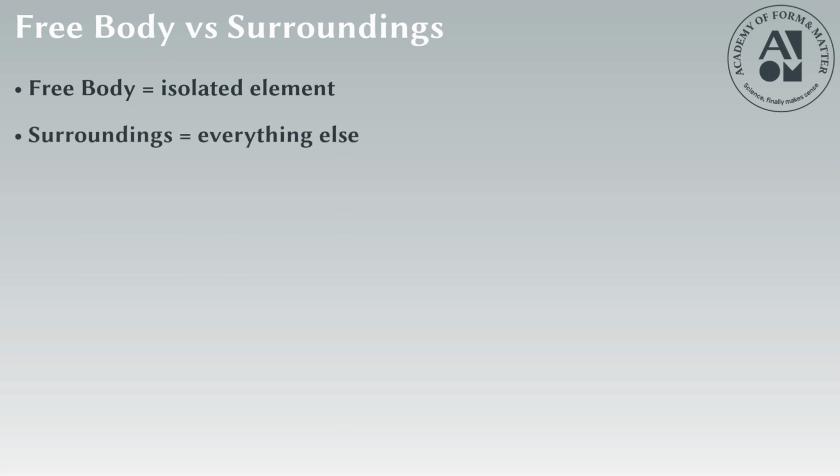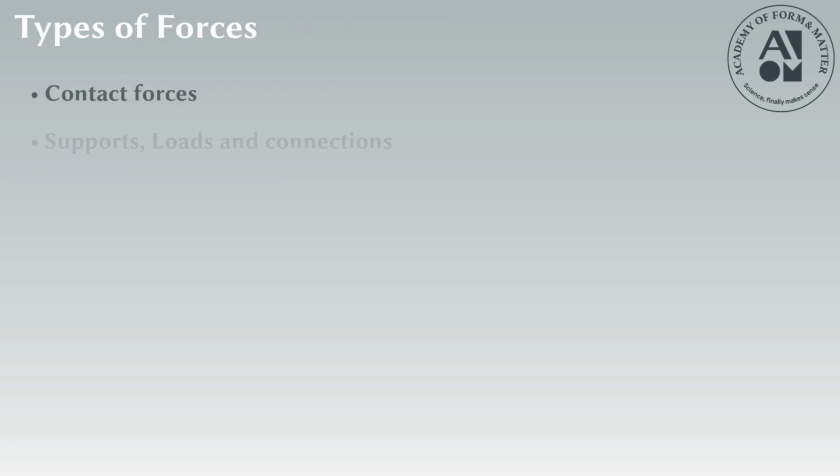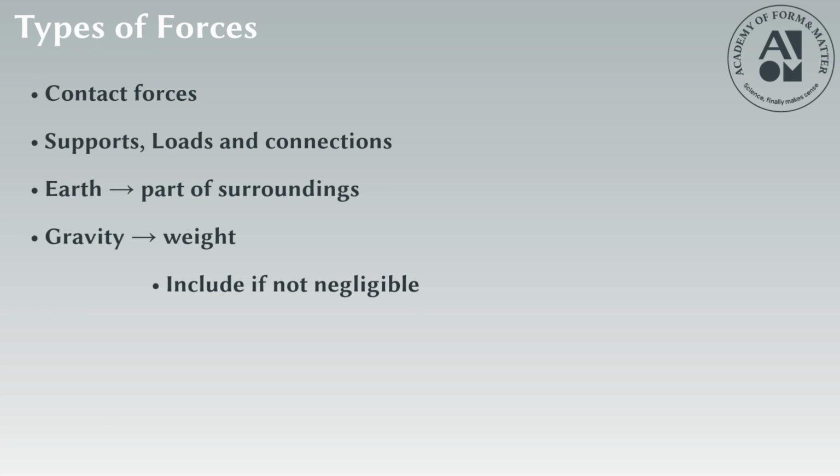And now something important happens. The surroundings don't disappear. They come back as forces and moments. Most of these forces come from contact, supports, connections, surfaces. But we should also remember that the Earth is part of the surroundings. Through gravity, it applies a force on the body, its weight. And unless this force is negligible compared to others, it must be included in the diagram.